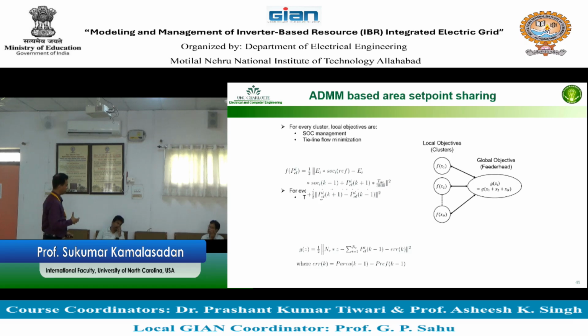Frequency regulation normally gets messed up if you have varying power from the generation or the load for that matter. So to regulate the frequency, the utility conventionally uses load frequency control, the AGC and the governor, the conventional centers. When DER goes in place, the generation varies, not the load.